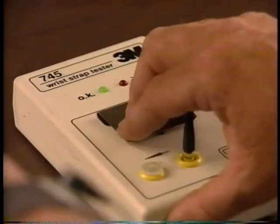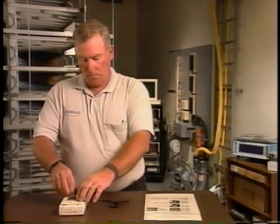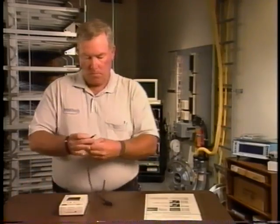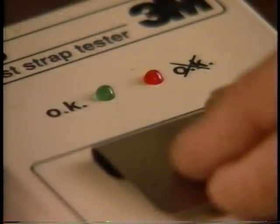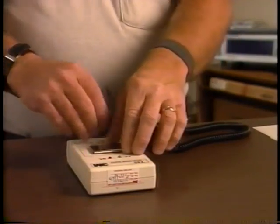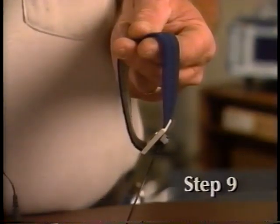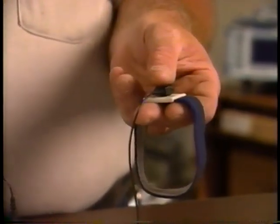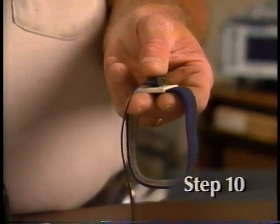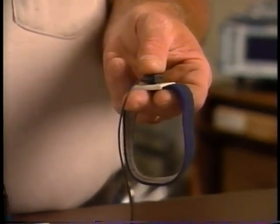If the pass indicator lights, the wrist strap and cord have passed the test. You may now unplug the wrist strap from the tester and begin work. If the fail indicator lights, replace the cord and return to step 2. Step 9, rotate the cuff 180 degrees. Step 10, put the cord connection and metal back plate between thumb and forefinger.